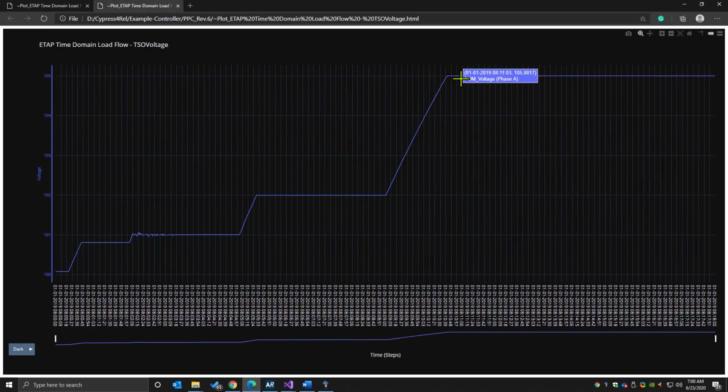And with a new size, we are easily able to achieve 105%. So of course there's fine tuning and precision required in adjusting the STATCOM size, but this is one of the strategies that can be used to make sure that you can meet the commanded voltage set point within a certain ramp rate and a certain reference value without any difficulty.